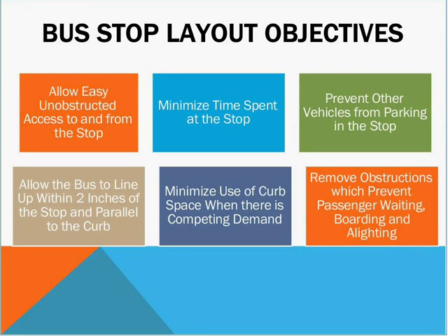When laying out the bus stop, as I mentioned before when the person mentioned scaffolding, the bus stop needs to be unobstructed, and there should be unobstructed access to and from that stop. If you have scaffolding and other things cluttering the sidewalk, we certainly can't accomplish that. It also becomes difficult if you have scaffolding along the curb to bring the bus close enough so that people can step off the bus onto the curb and not end up stepping into the street, which is an additional 4 to 6 inches, depending upon how many layers of new pavement have been placed on the roadway. We're talking about 4 to 6 inches additional if the bus is unable to pull up to the curb or to the bus stop area, which hopefully will have a curb.